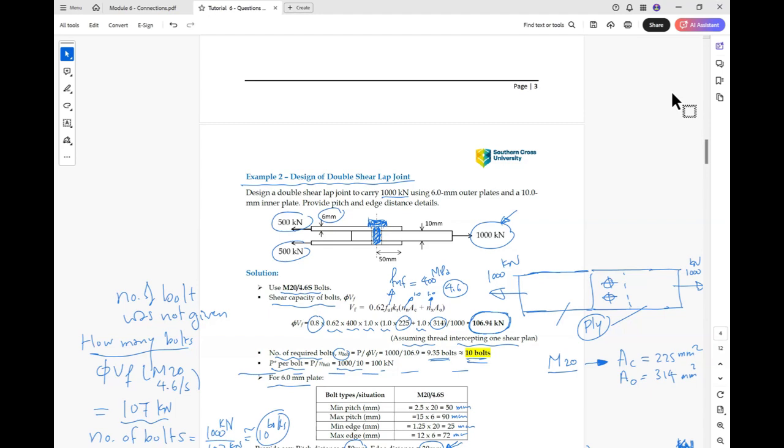You don't have to distribute the point load again or concentrate the uniform load again. Then with the combined loads, you can find the maximum load as one uniform load on the rafter and one point load on the rafter, and the 2 kilonewtons stays as it is on the column. Yeah, that makes sense.